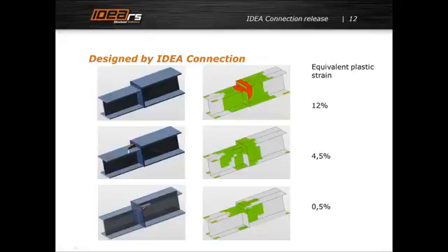We add, for instance, a very small haunch here, but even this small haunch really helps. And in fact, this design is good enough. But you can make it even better with stiffeners in the direction of the top flange of this beam, and such a design is perfect.